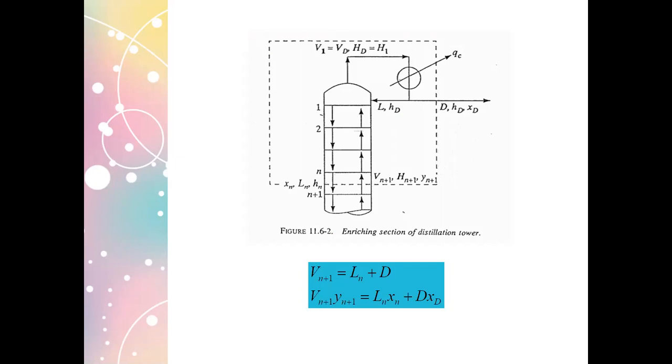What's a reboiler duty? When we speak of duty, what's the objective of the reboiler? It has to provide the energy necessary, that way a portion of the liquid that is flowing down your column is returned back into the column in the form of vapor. Otherwise, there won't be any vapor that will flow countercurrent to the liquid that is going down. That's the purpose of your reboiler. So when we speak of the reboiler duty, how much energy will your reboiler provide? That way, it will be able to turn the liquid to vapor.